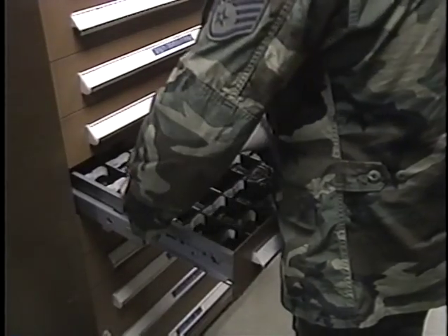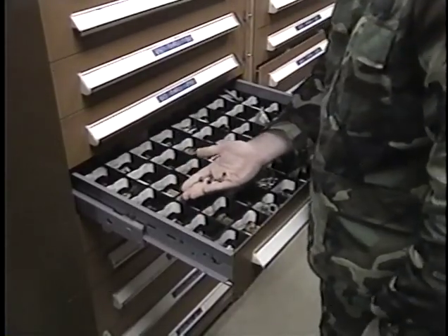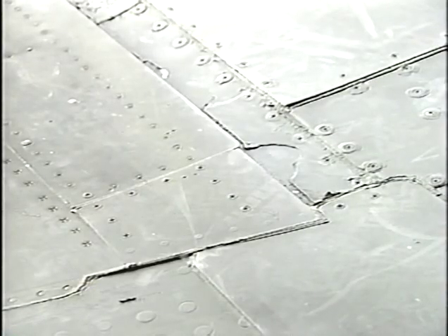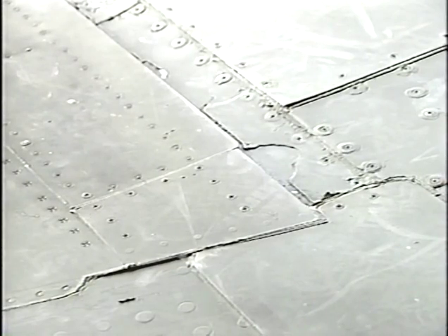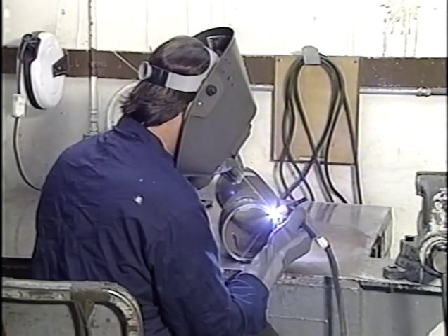We won't list all of the different aircraft and their corrosion-prone areas, but here are some general problems to be aware of. Fasteners are found in almost every area on aircraft and are often problem areas. These areas are subject to heavy operational loads, moisture intrusion, and possible corrosion from the surrounding aircraft skin. Spot-welded assemblies are highly susceptible to corrosion because of water entrapment caused by holes and gaps created between the parts.